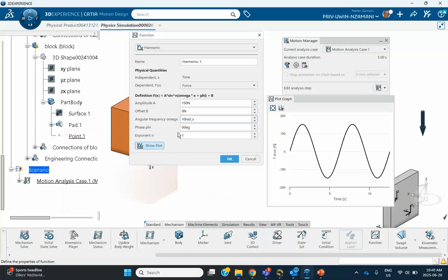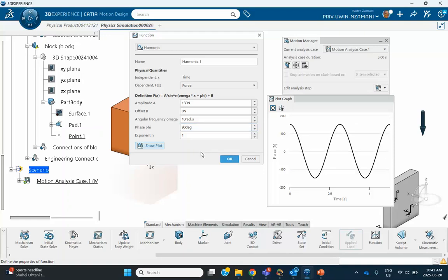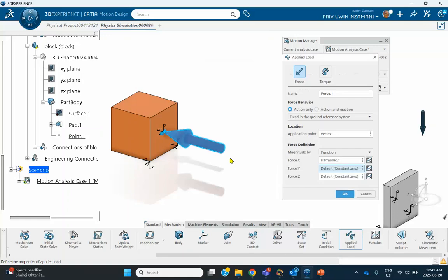If you look at the plot, it looks like that. This is the plot for time zero. Cosine is going to give you this. It's not going to be 0, so we have to fix it. Offset, there are different ways of doing it. So this should be 90. It should be 90. Let's check, because otherwise you get sine. Yeah, that's good. You've got to be careful about this. It doesn't matter in the steady state solution, but for the transient one, it does matter. We say okay, and then we say okay. Very good.